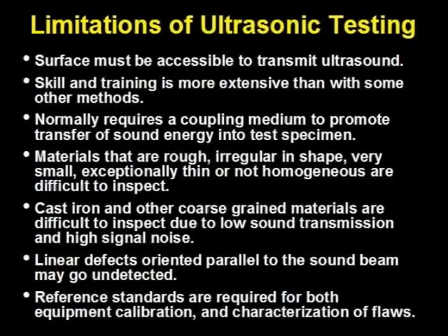Ultrasonic testing has several limitations. The surface must be accessible to transmit ultrasound. The skill and training required is more extensive than with some other methods. Ultrasonic testing requires a coupling medium to promote transfer of sound energy into the test specimen.